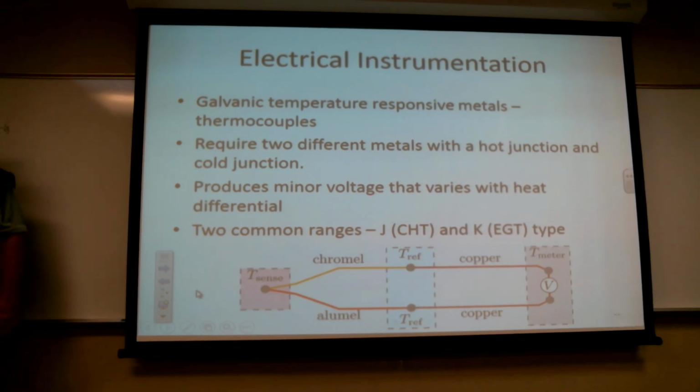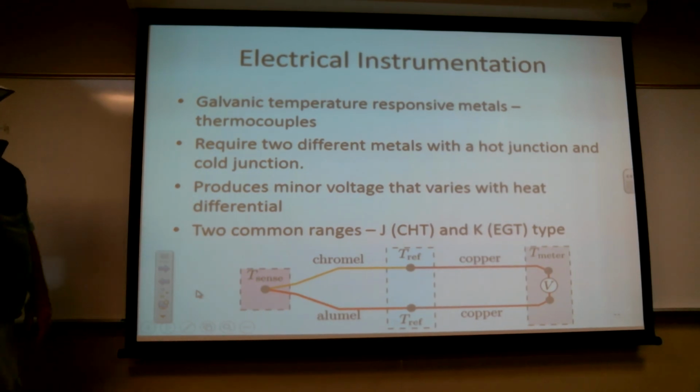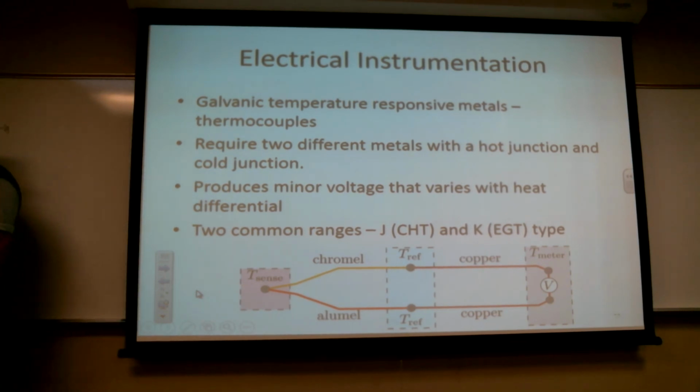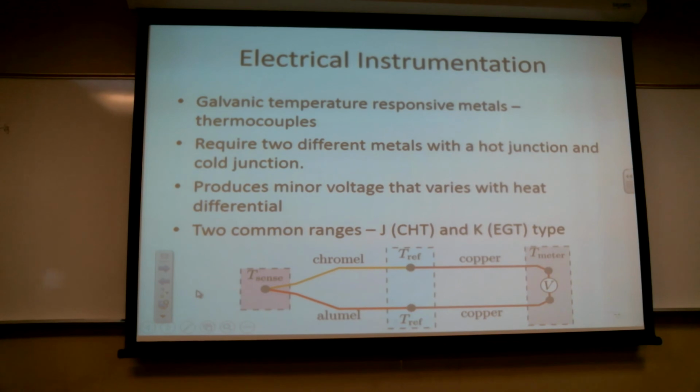It's a small amount of voltage, it's a small amount of current, but we don't need a whole lot. And the upside is within a given range, it's fairly consistent, fairly accurate. So CHTs, what do we typically see in cylinder head temperature? Basically 200 to 500 degrees C. Pretty much not much more than that. At 500, you're doing damage, okay?